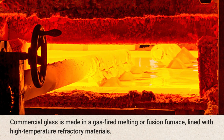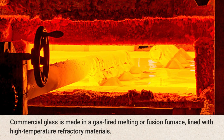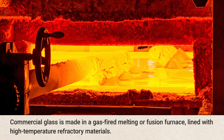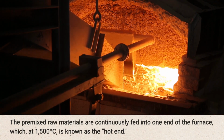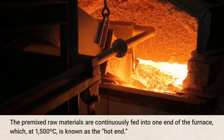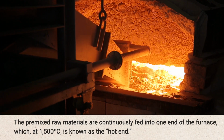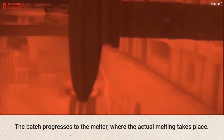Commercial glass is made in a gas-fired melting or fusion furnace, lined with high-temperature refractory materials. The pre-mixed raw materials are continuously fed into one end of the furnace, which at 1500 degrees Celsius is known as the hot end. The batch progresses to the melter, where the actual melting takes place.